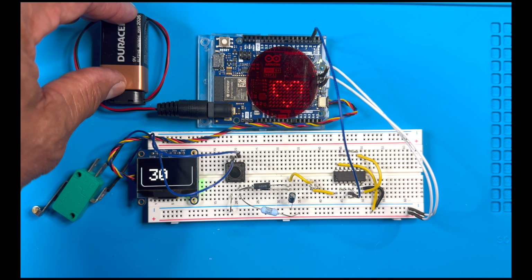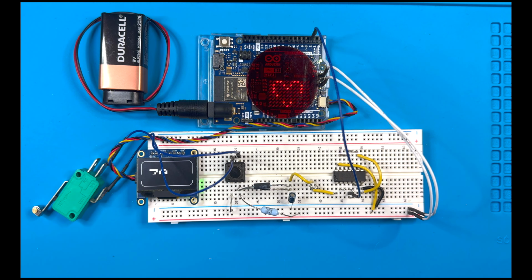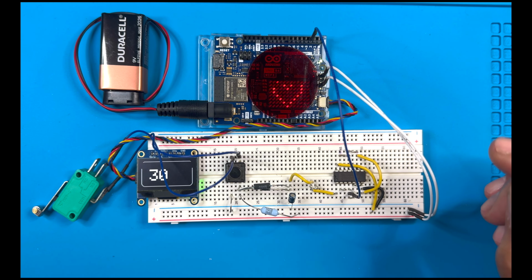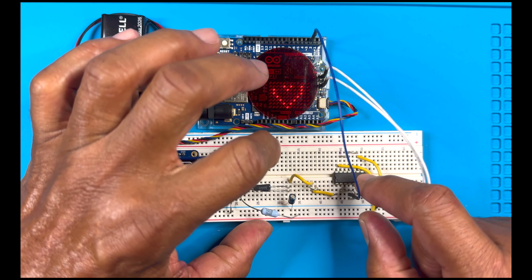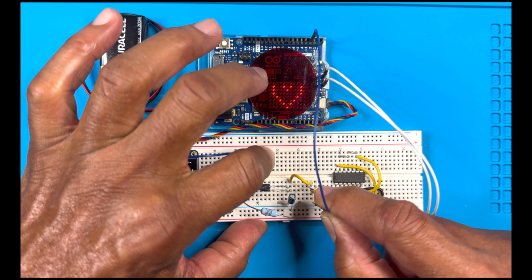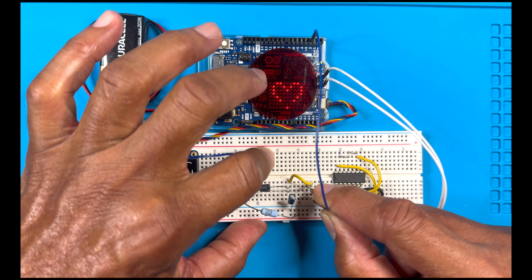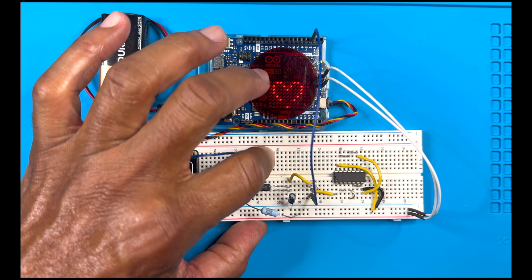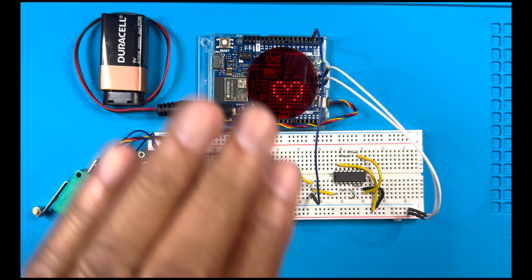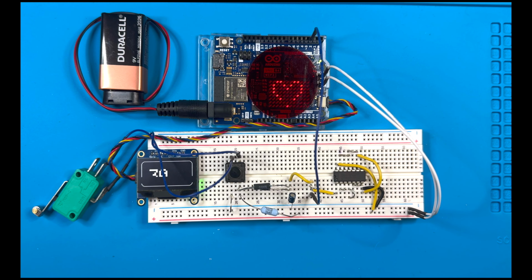Now, both your Uno R3 and R4 have inputs with a hysteresis built in, with threshold levels already built into the processor. So let's move this back over to before the input to the Schmitt trigger. Now we're using essentially just the RC network without the Schmitt trigger, and theoretically the processor should be able to handle that.